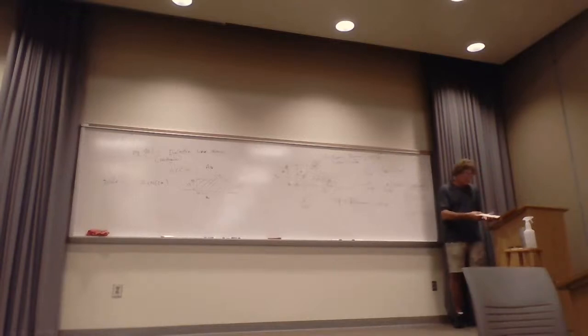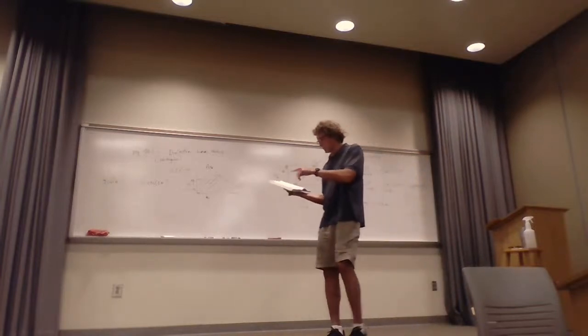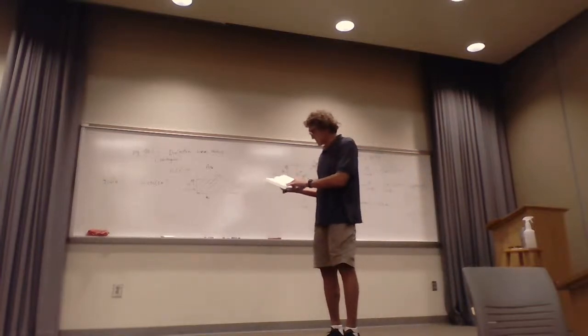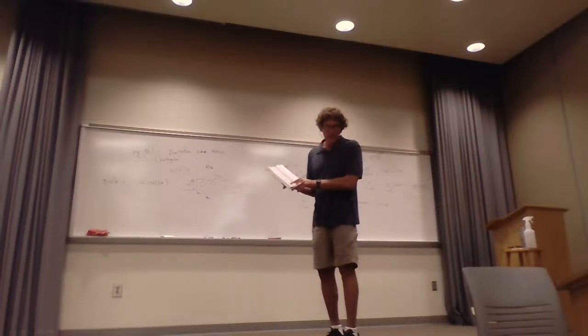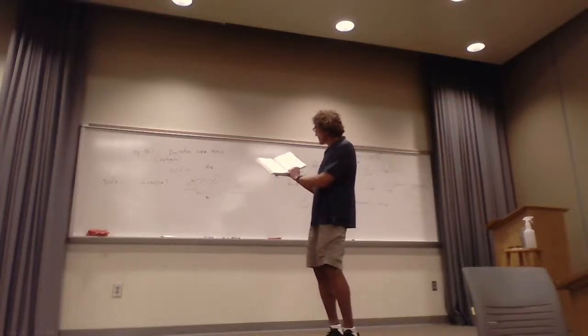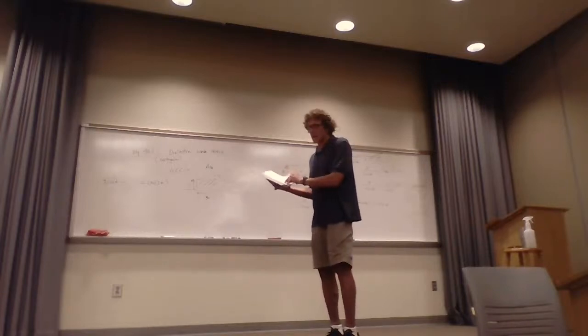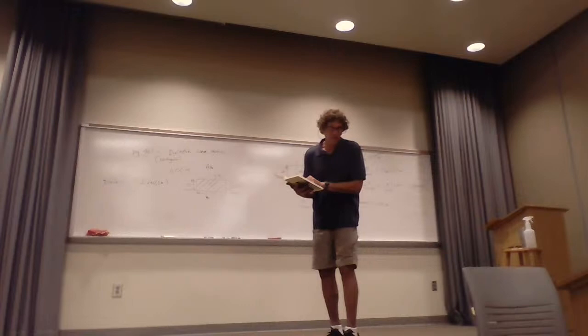What he does is show you graphically, if you have TE versus TM modes, how you plot one side of the equation versus another. You're plotting both versus angle theta I. And where there's intersection, those are the allowable points where it can operate. You all see that? I'm not going to ask you to do this. Just please appreciate it. For the TM mode, he shows it at the bottom of page 403. In either case, you're solving this iteratively. But all this doesn't mean much to you.